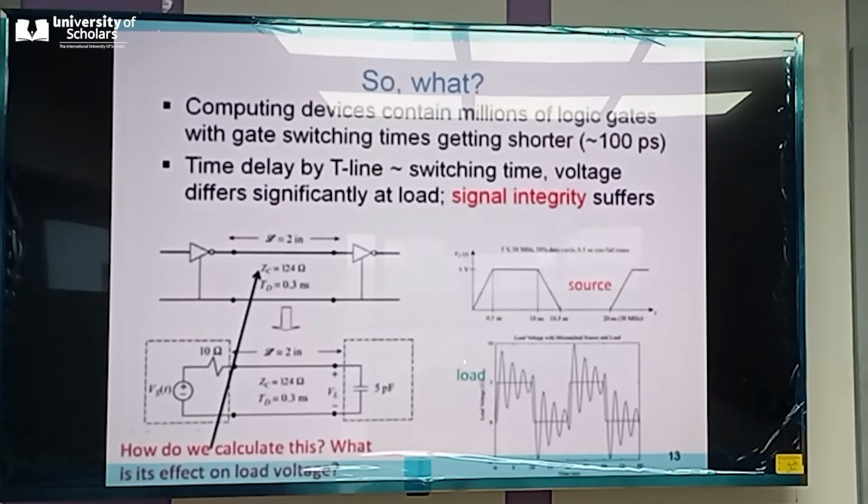And this is switching from logic low to logic high in about 0.5 nanoseconds. Okay, the delay is of 0.5 nanosecond. And thereafter, it is constant for about up to 10 nanosecond and then switches back to logic 0, logic low, again with an interval of 0.5 nanosecond, which I have explained on the board. This is at the source end. So we were talking about the source end.